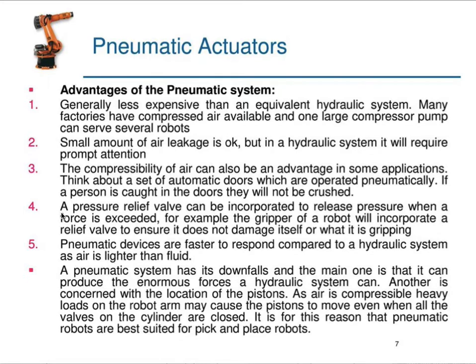As the fourth one, a pressure relief valve can be incorporated to release the pressure when a force is exceeded. For example, the gripper of the robot will incorporate a relief valve to ensure it does not damage itself or what it is gripping.